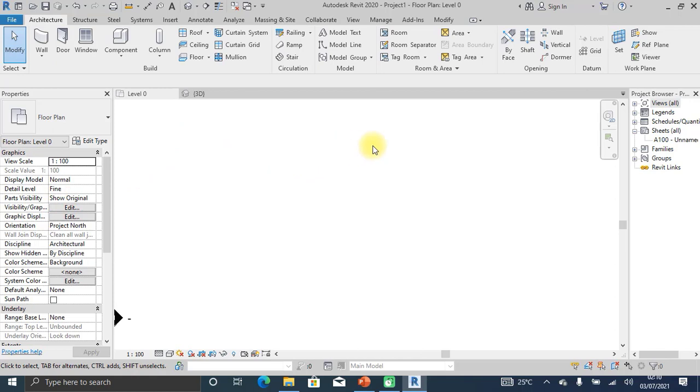So this is the workspace, and you see we have these 4 callouts that are there by default. So you really have to create levels in Revit Architecture to specify the floor platform levels for each of your floors in a multiple story building.